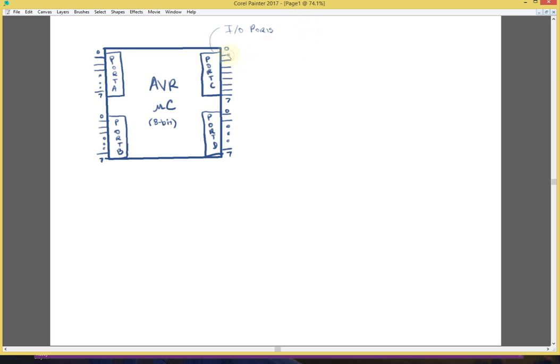So for example, we can attach to this pin an LED that lights up whenever pin 1 is turned on, and it turns off whenever pin 1 goes to 0, assuming that it's wired this way. We could have another pin control a motor, say, and I'm oversimplifying just to get the point across. Usually there is some interfacing circuit that would be necessary to interface this digital device to an analog device such as a motor, but I'm just trying to get the point across.